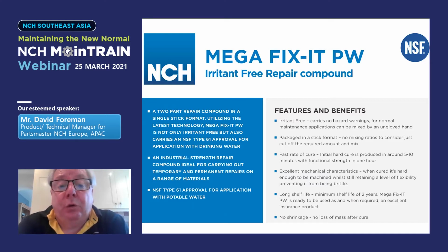The most important feature of this product is basically it is NSF approved for contact with potable drinking water, which is very, very important. It's packaged in a stick format, so no mixing ratios to consider, as you've seen. It has a very fast cure rate. Initial hard cure is produced around 5 to 10 minutes. With functional strength, you can actually machine it within 1 hour.